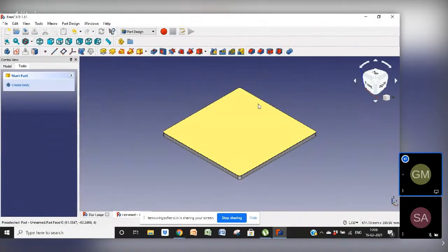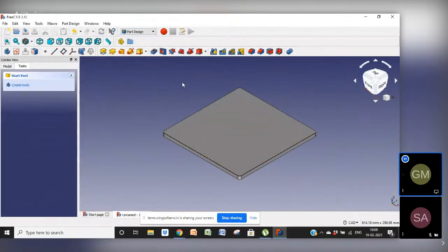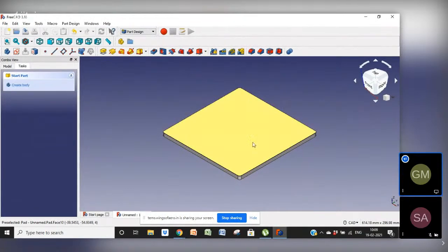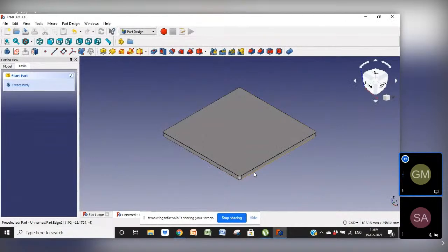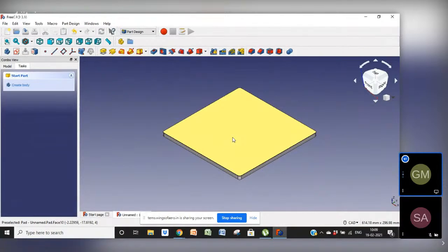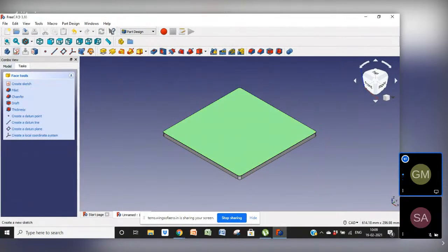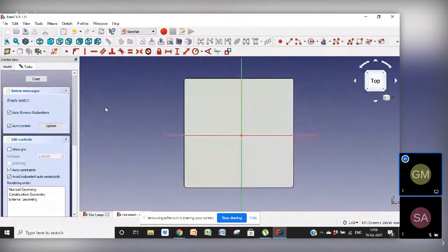If we choose that 50 mm, then we need to cut it from these sides so that we can make it hollow. Now we have this base plate. Here we will make spot plates or spot screws on the four corners and then a covering plate. For the spot screws or studs, I will make a sketch over this face. Here you can choose even a circular or an angular spot, whatever you want.